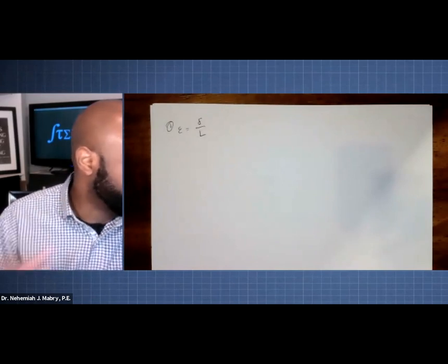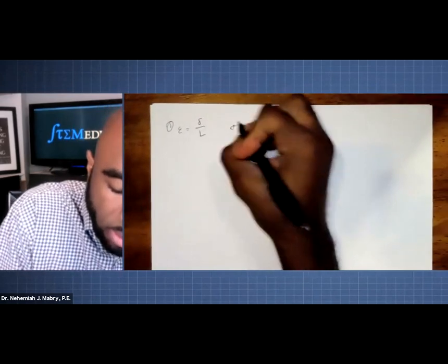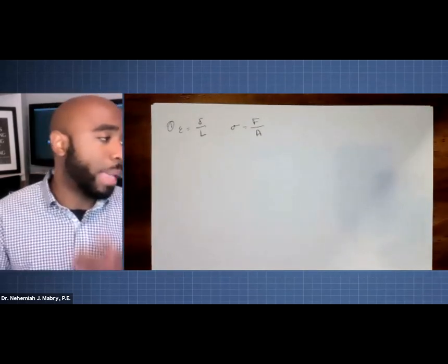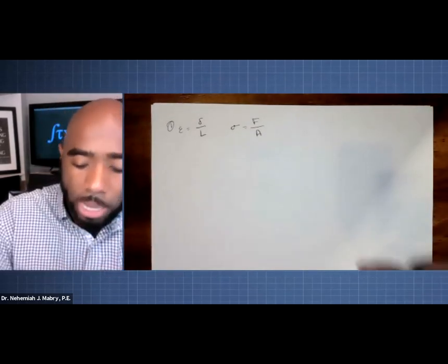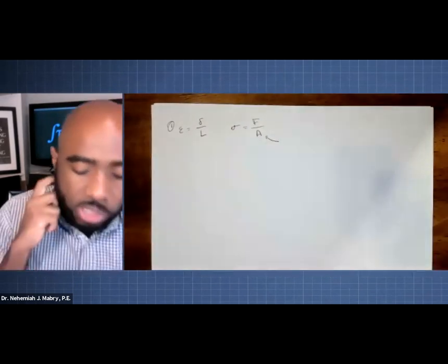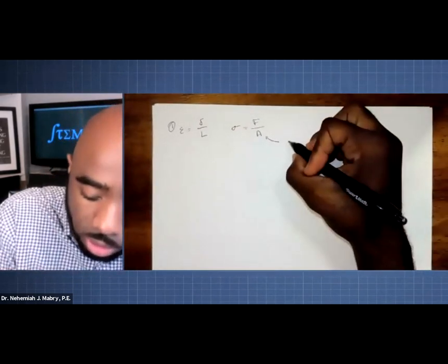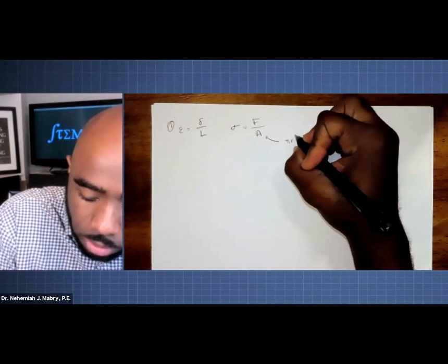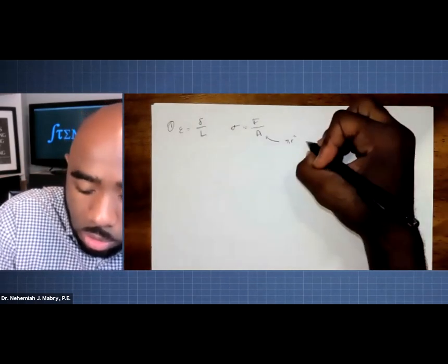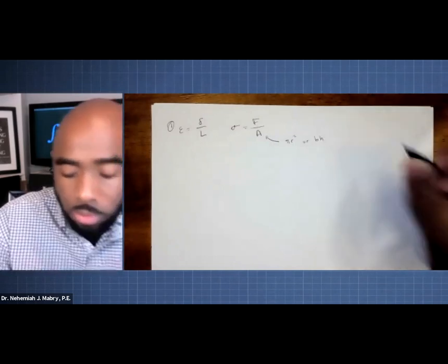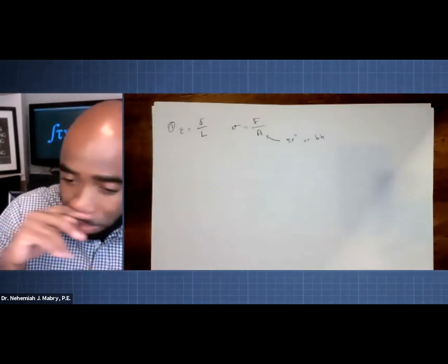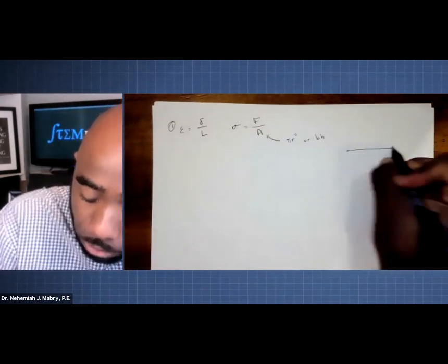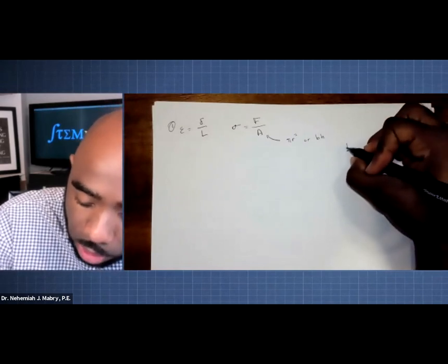You also want to remember the basic equation that stress is basically force over A. Keep that in mind. Sometimes, depending on the shape of whatever is stretching, you want to make sure you remember the area. If it's a circular area, pi r squared, or if it's rectangular, base times height, right? Keep that in mind. And what you'll probably be given is, let's just say, some sort of setup where maybe you have a distributed load.